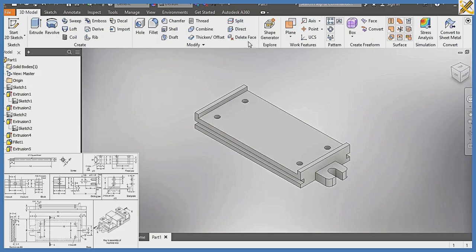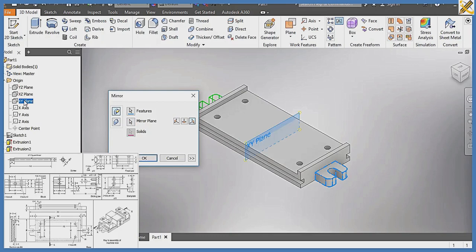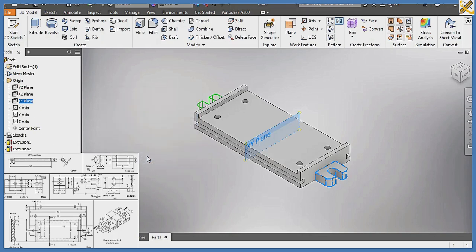I'm going to click on mirror. Clicking on my mirror, I pick the full component. So mirror plane, coming towards origin, that should be the XY plane. All right, then, okay, you can see it is not replicated right there though.